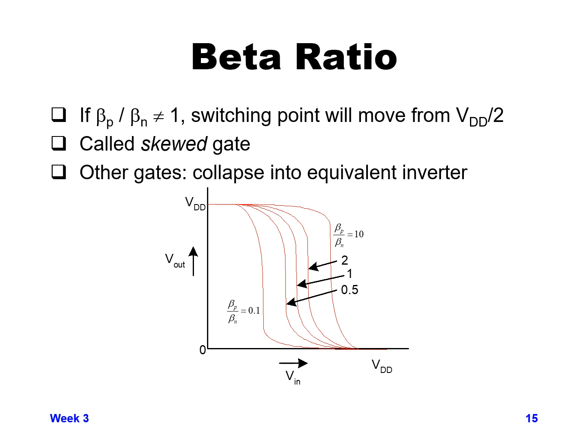And the reason for that is, as the PMOS device gets larger, in order to equalize the current between the N and P, to cause your Vout to hit the middle, you need a higher voltage on your NMOS gate to pull more current through the NMOS, and the higher voltage on the PMOS causes it to have less current. So you need a higher voltage to get the NMOS larger current, PMOS smaller current, such that they equal each other and cause that high switching point.